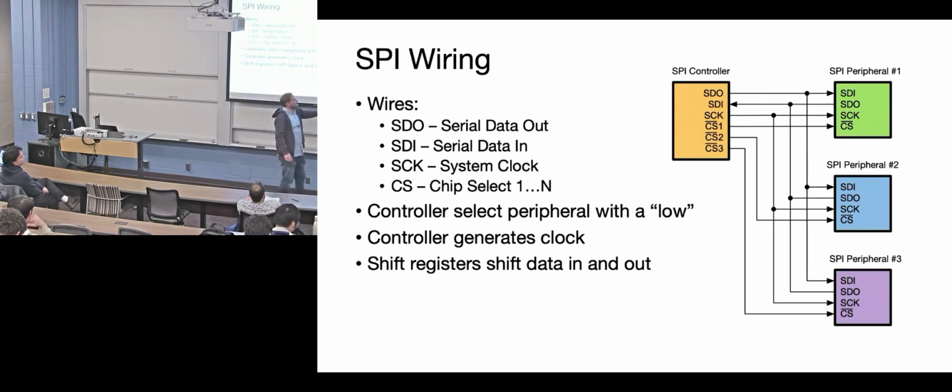That's why many peripherals now, like if you had an accelerometer or something, you have to send an extra wire back as part of an interrupt line or control line. There's no interrupt capability built into SPI, even though it's often needed for an application.